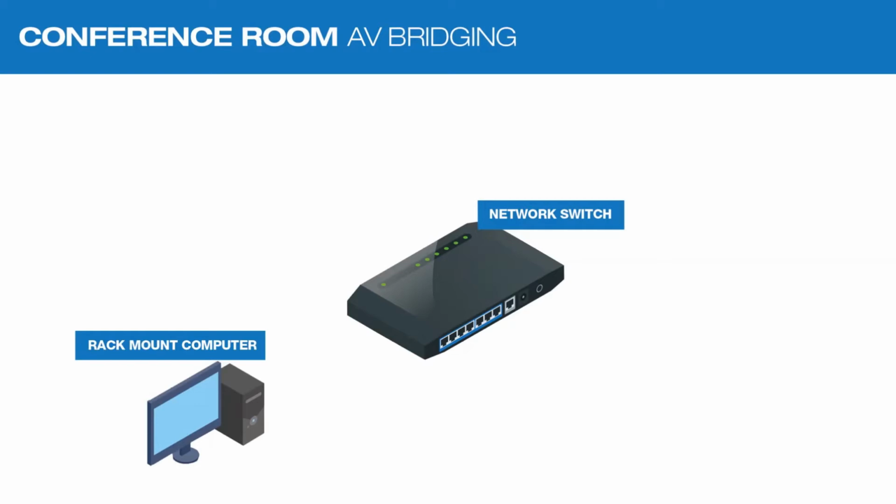The advantage of network is that it's not necessarily point-to-point. Cat5 cable has got a limit of 100 meters, which is much more than USB and HDMI. Without the need of any extenders, you can terminate in field. Yeah, you can basically scale this the way you want it.